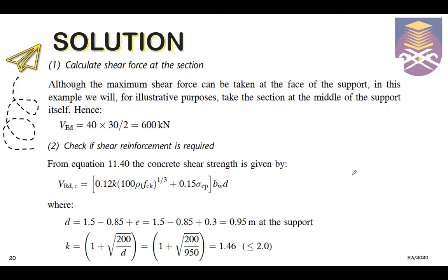So we are going to start with the calculation. We have here the VEd value. Then we check whether shear reinforcement is required. So we are going to go to the flow chart from just now, and compare the value of VEd with VRd,c first, using this equation.